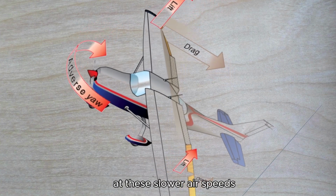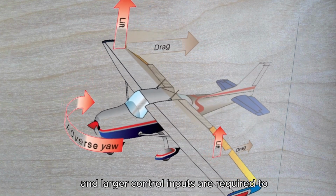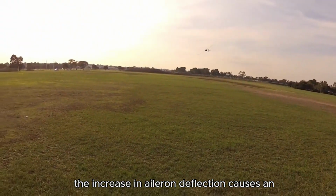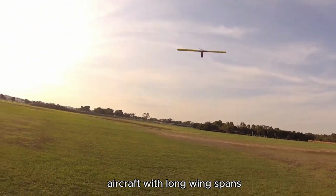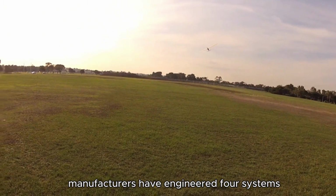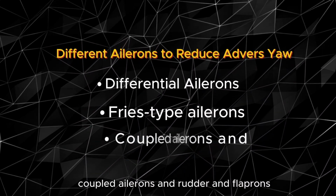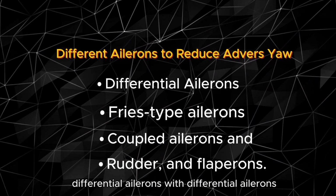At these slower airspeeds, aerodynamic pressure on control surfaces is low, and larger control inputs are required to effectively maneuver the aircraft. As a result, the increase in aileron deflection causes an increase in adverse yaw. The yaw is especially evident in aircraft with long wingspans. To reduce the effects of adverse yaw, manufacturers have engineered four systems: differential ailerons, Frise-type ailerons, coupled ailerons and rudder, and flaperons. Differential ailerons.